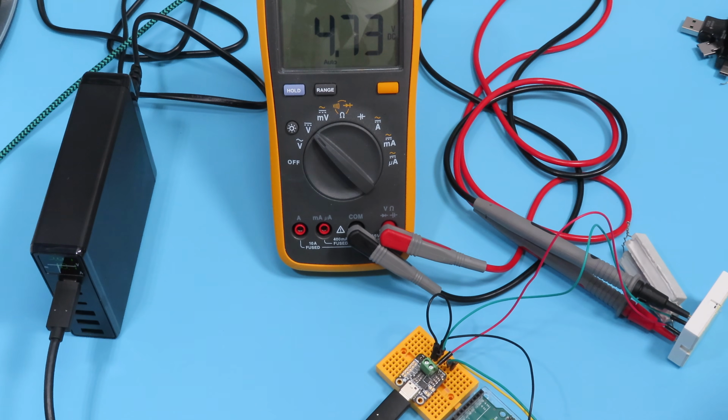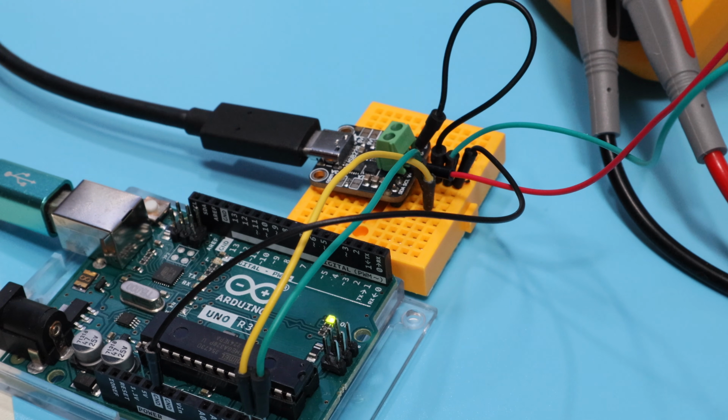So this is a pretty versatile adapter, and actually as a trigger board, it's not that much more expensive than ones that don't use I2C. And of course, you can use it just as a standard trigger board by using the jumpers, or you can use it programmatically and program it for voltage and current yourself using the Adafruit library.